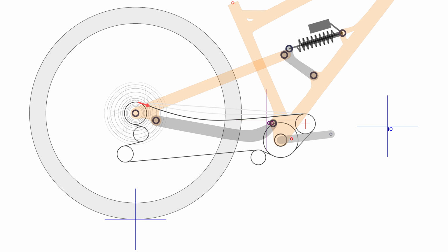If the cassette is disengaged, then the extra chain length caused by flexing is again compensated by the lower chain segment. But the inertia of the lower part of the chain resists the cassette rotation that is necessary to move the chain links to the upper segment. In this situation, the cassette behaves like a pulley. The wheel is being pulled down from the weight of the chain slapping on both the lower and upper part of the drivetrain. This is what is generally referred to as chain flail, and it can also cause unwanted chatter at the rider's feet.